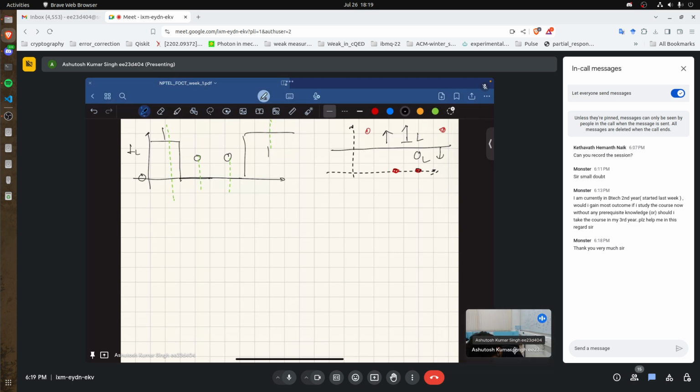So a few things to note here. What is the quantization level? Quantization level just means how many discrete steps in the y-axis. So there are two discrete levels. What are the two discrete levels? One is level 0 and the other is level 1. So this is called quantization level.